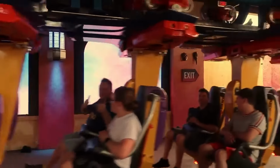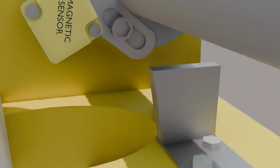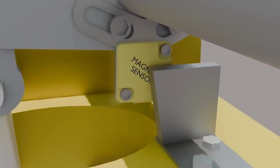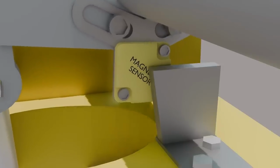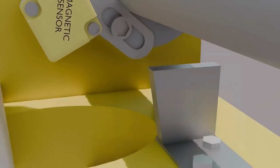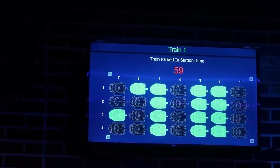These types of restraints often feature seat sensors. This is a system that communicates with the ride's control system the secured status of each individual restraint. These are found on other restraint types too, but are most common on hydraulic systems as there's already electricity being supplied to the train. Seat sensors consist of a magnetic proximity sensor mounted to a part of each individual restraint.